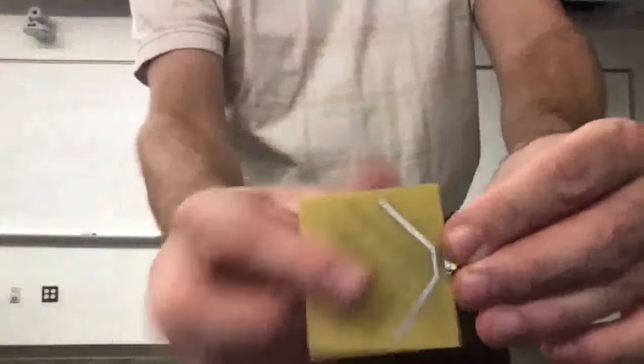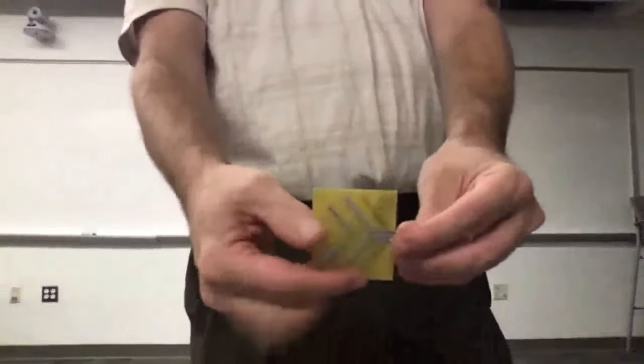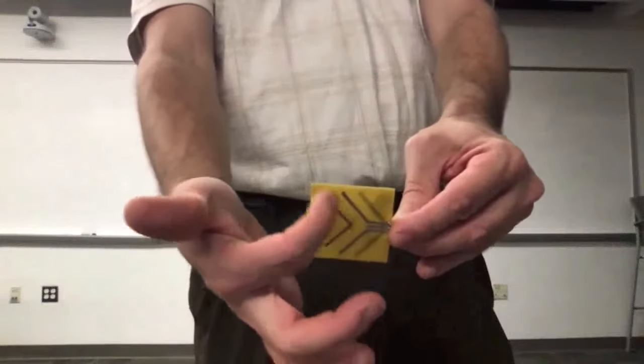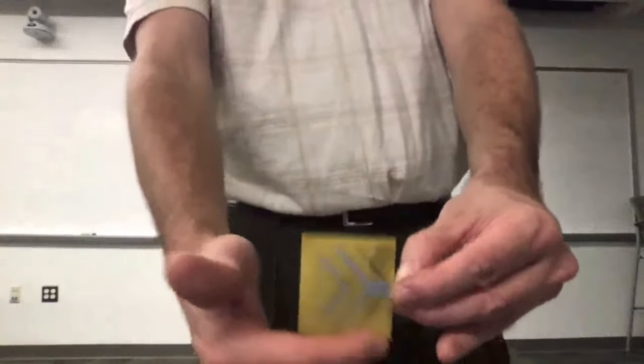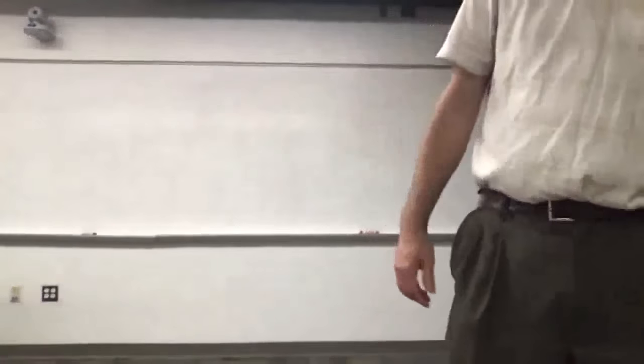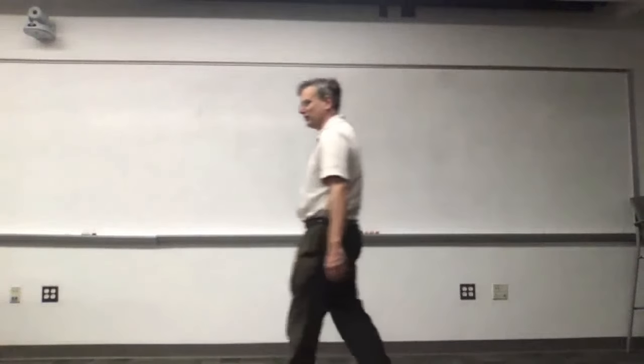We've got 2 up here, and then the reflector. The director and the reflector aren't connected to anything. They're just true parasitic elements. But the director's on the back so that the trace can go. The reflector is on the back because the trace has to go and feed this director here. We'll look at that later after class when you're done with lecture. Okay.